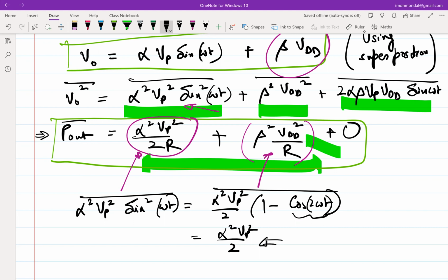So I times V becomes essentially V times V by R. So that's why you are getting V squared by R, right? This act doesn't change the frequency component of the signal. The act of finding out the power is not changing the frequency component. But the important thing to note here is that this power that we got is the power carried by the sinusoid at omega, not 2 omega, at omega.